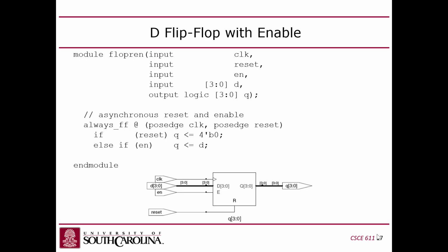Now, this problem has kind of gone away because in SystemVerilog, we have this difference between always_ff and always_comb. If you use always_comb, you're telling SystemVerilog that you're intending to make combinational logic. So if you make that mistake, you'll get an error message. You'll know you made the mistake. And this is the reason why we have different always statements. In regular Verilog, which is what we taught in the past in this class, that was a big concern, but I think this hopefully will fix the problem, I hope.